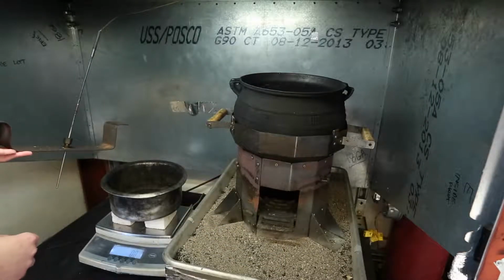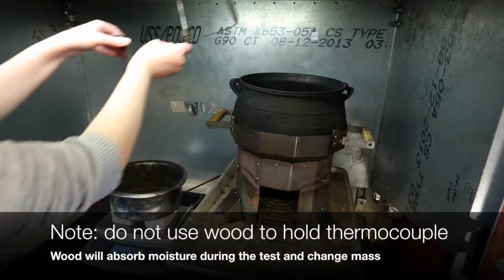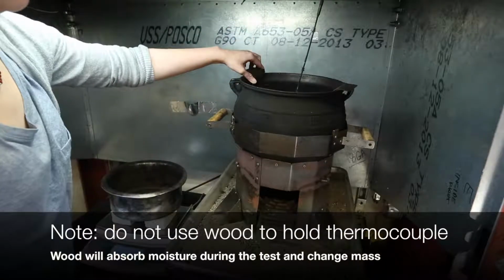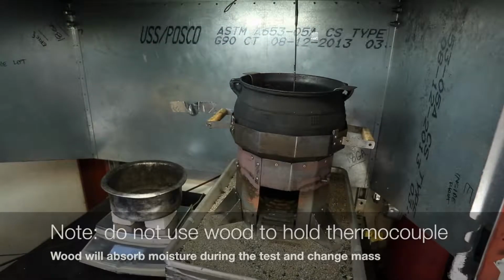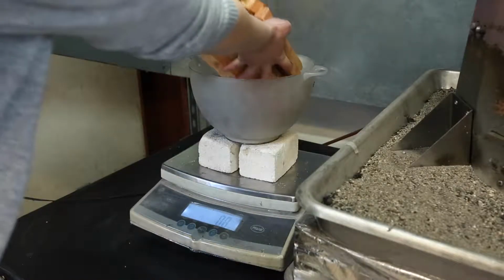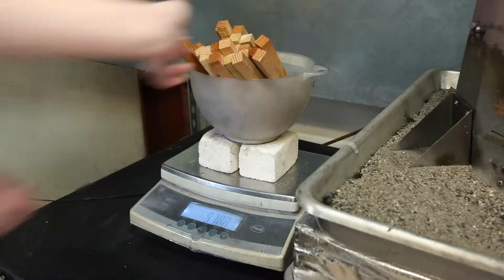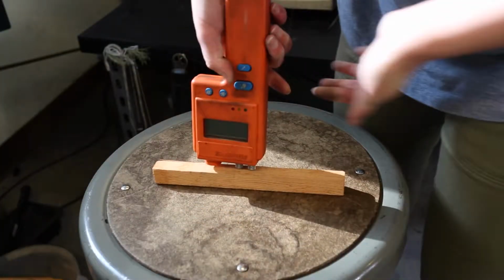Although not shown here, you may find it useful to measure other parameters such as the weight of the pot, the weight of the thermocouple probe and its holder, and the weight of the stove. The fuel we are using today is air-dried Douglas fir. We had previously submitted samples of this wood and its corresponding char for heating value analysis, so all relevant lower heating values are already known and thus do not need to be measured today.